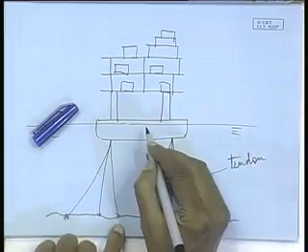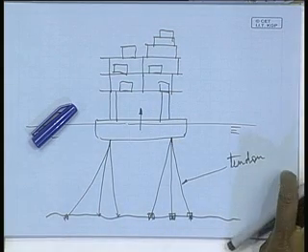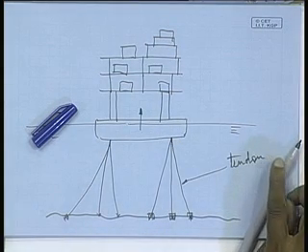But if you try to press it down further, you feel an upward thrust, right. Same thing, instead of pressing it down, I try to pull it down. That is what is done here. It is pulled down, that means these tendons are in tension. Why? Because when you are pulling it down, it has a buoyancy, so it tries to float up, that means the upward thrust automatically works. That is what is a positive buoyancy, right.